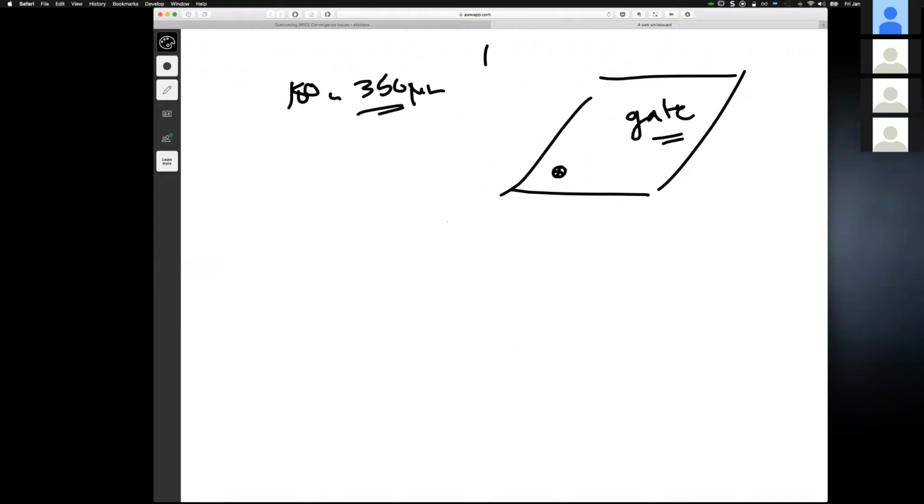And that becomes very common when you go down to processes like 45 nanometer, etc. Actually, just the whole gate oxide integrity effects and the defect density related, we have to put rules in based on the sizes, just based on the statistics of the process, not because of optics or anything, but the statistics.